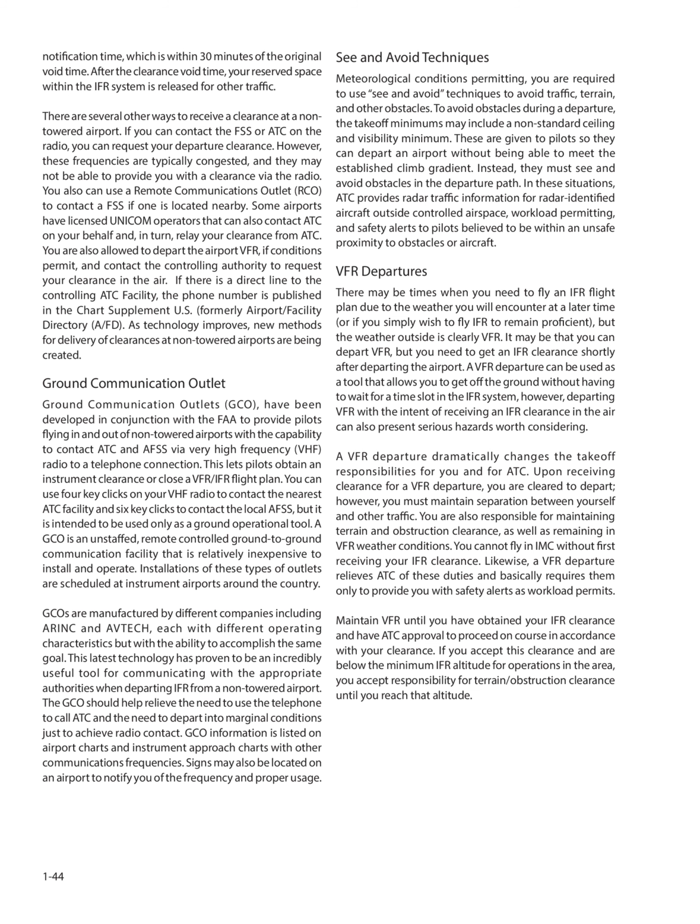Departing VFR with the intent of receiving an IFR clearance in the air can also present serious hazards worth considering. A VFR departure dramatically changes the takeoff responsibilities for you and for ATC. Upon receiving clearance for a VFR departure, you are cleared to depart. However, you must maintain separation between yourself and other traffic. You are also responsible for maintaining terrain and obstruction clearance, as well as remaining in VFR weather conditions. You cannot fly in IMC without first receiving your IFR clearance.